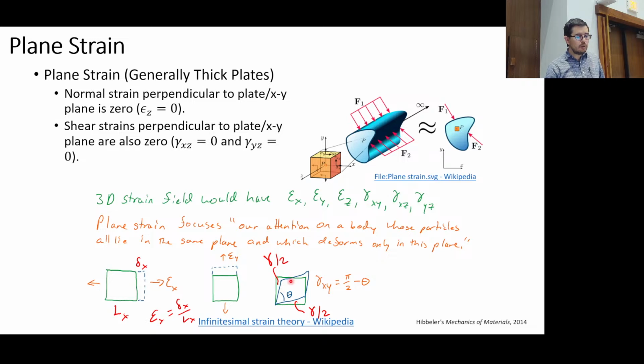The angle is larger, okay, the resulting angle is larger in these other two corners, and it's smaller than the 90 degrees in this corner up here too, right? So that's positive strain. If you have negative strain, then what happens is this parallelogram actually expands out beyond. So you would have something coming off this direction, a little bit and coming off this direction, and then this angle in this corner and this angle in this corner, that'd be a little bit smaller, right? Just to give an idea of what positive and negative shear strain really look like.